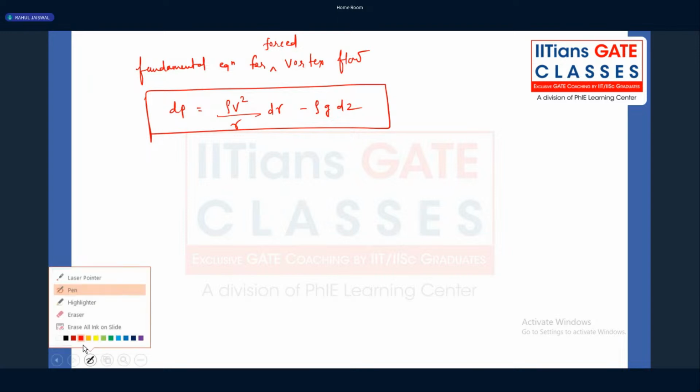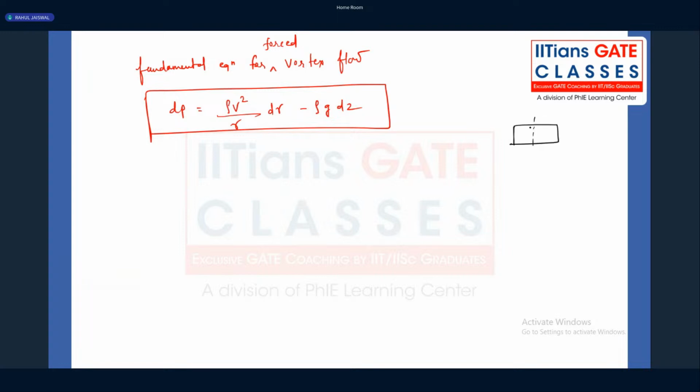But they are not asking, basically, there's no variation of height. Because whenever the tank is rotated about a certain axis, we are calculating from the center to a point A, from 0 to here. So we are taking both points on the same level, so this will not be coming into the picture.